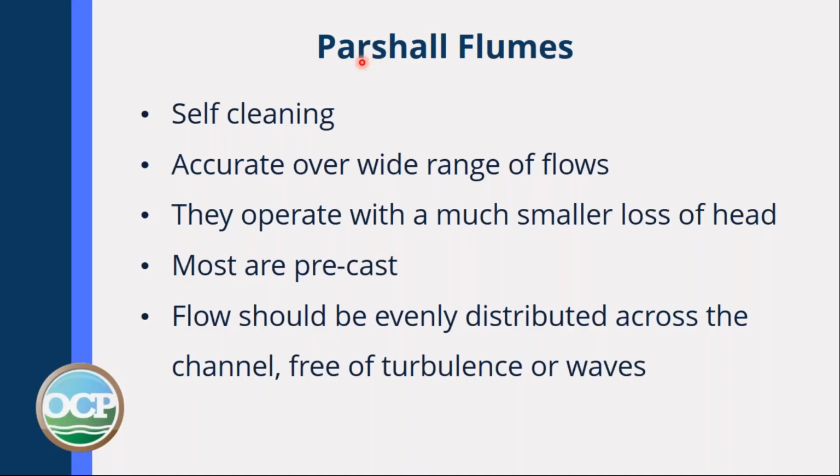They operate with a lower loss of pressure or head. Again, I mentioned earlier that most of them are pre-cast, pre-formed, and so they don't have to be constructed on site. But you need to make sure that there is as little turbulence as possible during the flow of that water through the flume.